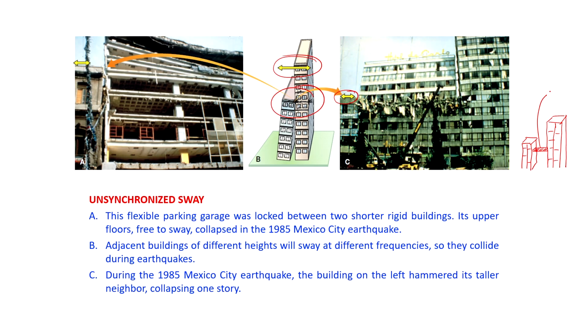This is again not a good idea, even if taller buildings of the same height are connected, because they have different sway patterns, and this is going to be experienced. This is the best example of that, in the 1985 Mexican earthquake: unsynchronized sway of taller and shorter buildings.